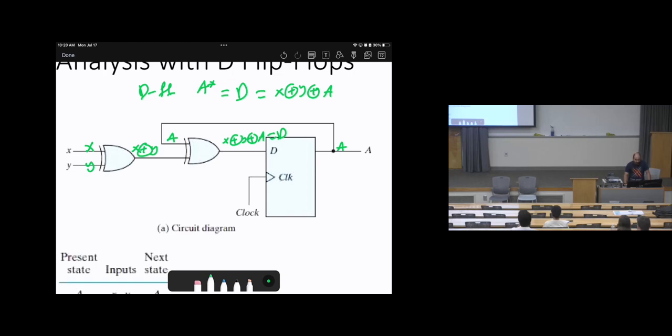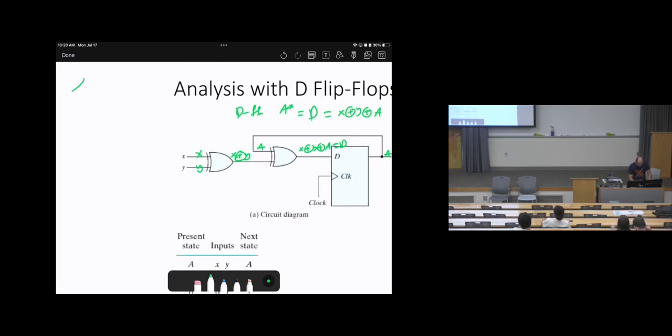Now, do we need to make the exclusive OR to find the equations? Yes, you can, but sometimes it can take so long. Here we need to make the truth table or the state table. Remember, exclusive OR is an odd function, meaning count the number of ones.